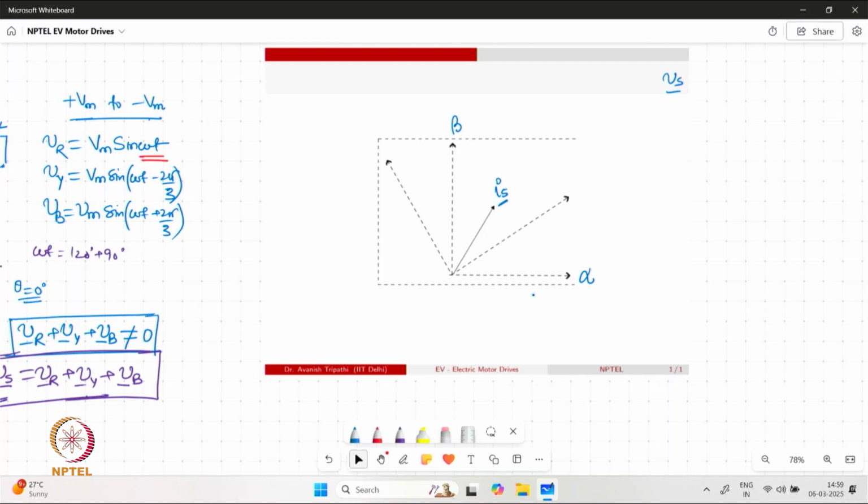Now when we are dealing with the machine and we have the rotor where windings are located and current vector IR is represented in that, we essentially say that there is a frame of reference alpha r beta r attached to the rotor with respect to which we are writing our current vector IR.